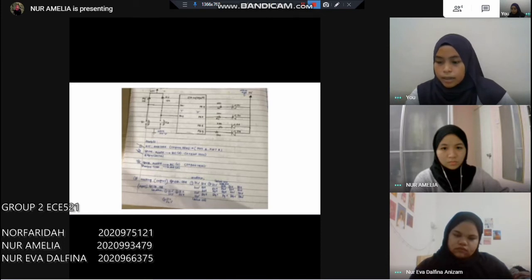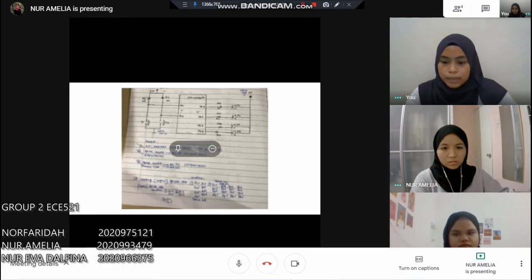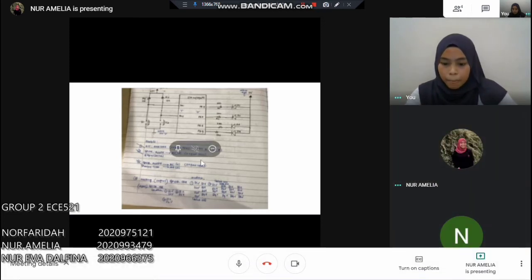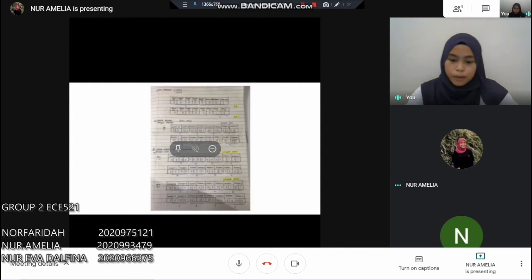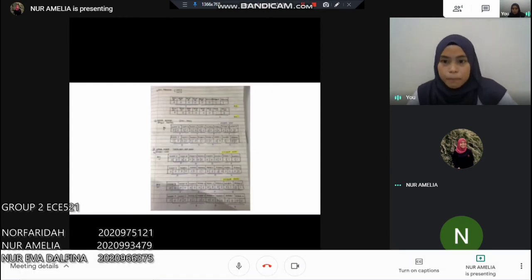GPIOA IDR, we have our address 0x40020010. And lastly, GPIOB ODR, we have our address 0x40020414.